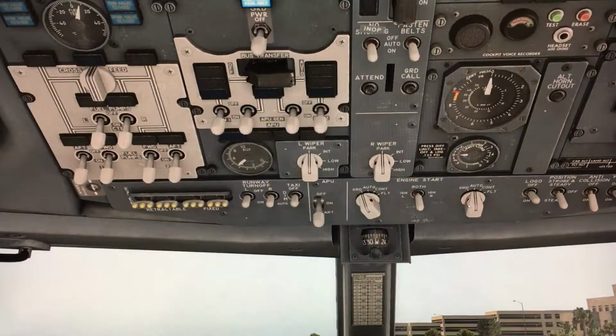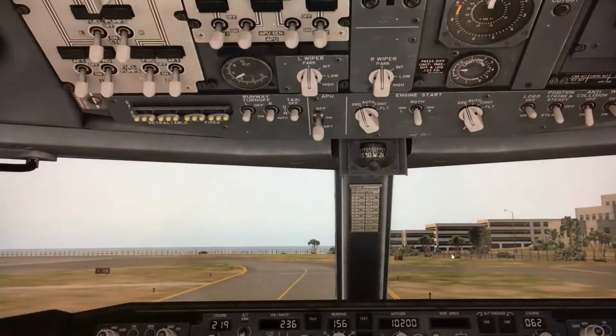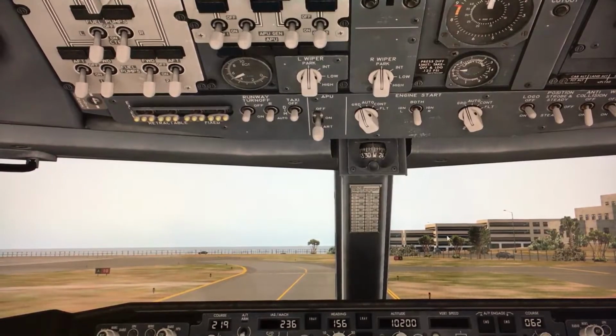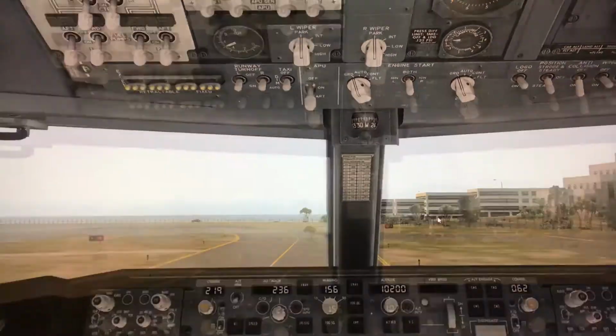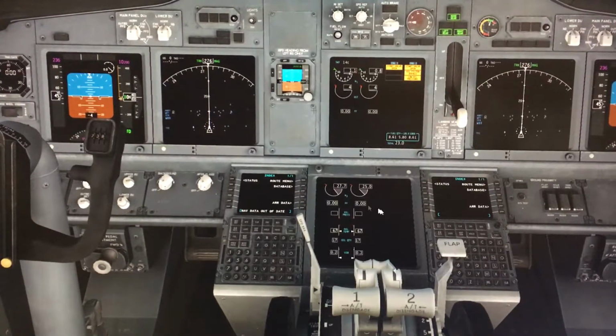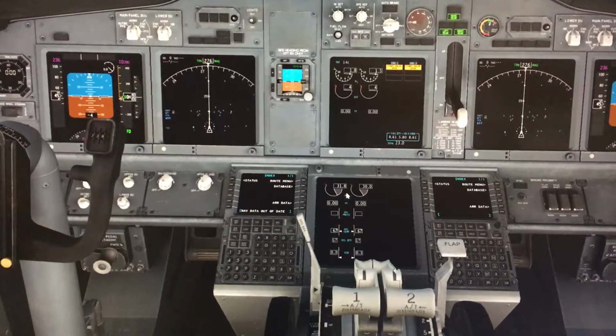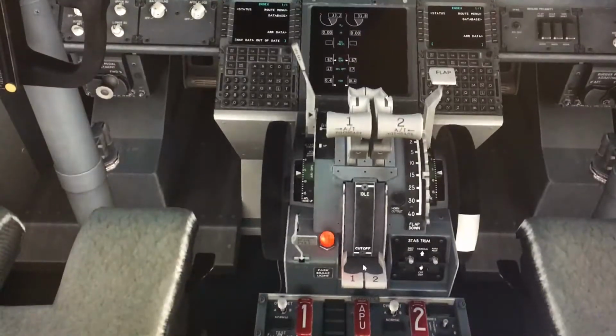Go to the engine start panel, using the feeding air and APU power to turn the engine to some kind of RPM before we pump the fuel into the engine to get it started. On this engine display panel, there are two numbers. Once the number hits 20%, or 20, you can put the engine from cutoff to idle. And once you do that, the engine will run totally on fuel. So the starter will automatically stop and go to normal operating mode.